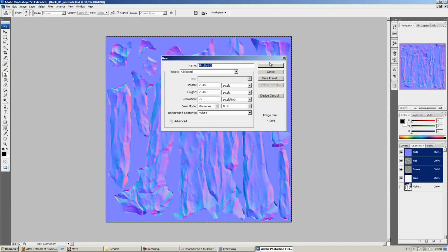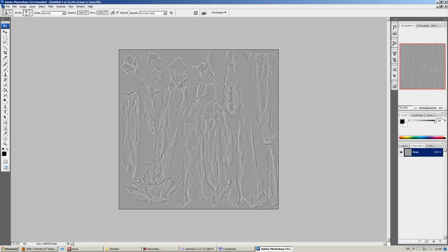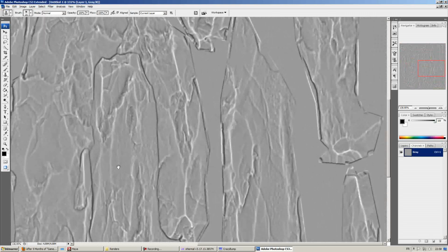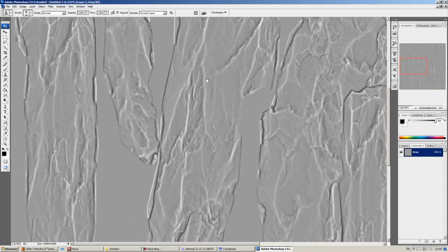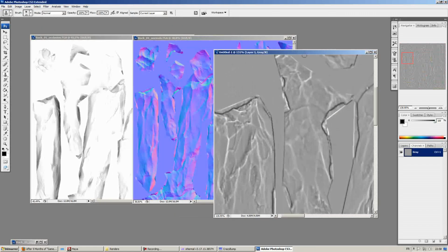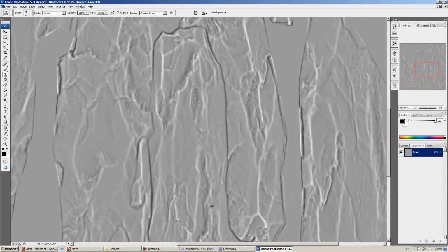Then go to Photoshop and create a new document. It will automatically set the size because you have a document saved in the clipboard. And you just Control V to paste the texture. Now this texture could be used as an overlay on top of your color texture, and it will help you define the edges of the rock and some of the cavities. So this is one way of doing an edge highlight map which has cavity information. So you could save some time.